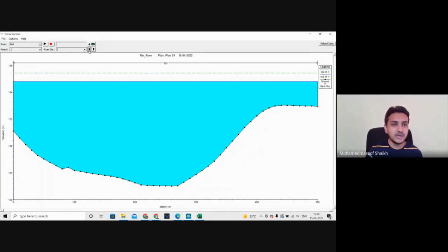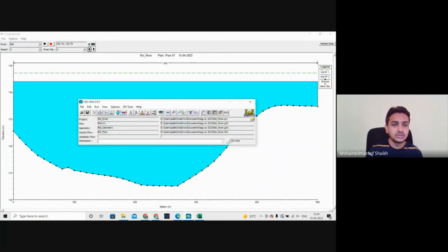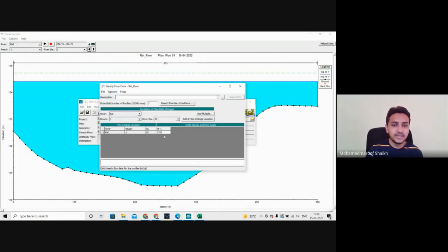Okay, so now I am changing the discharge. For that, I need to go to steady flow data. And instead of this 3355, I am replacing it with 3000.